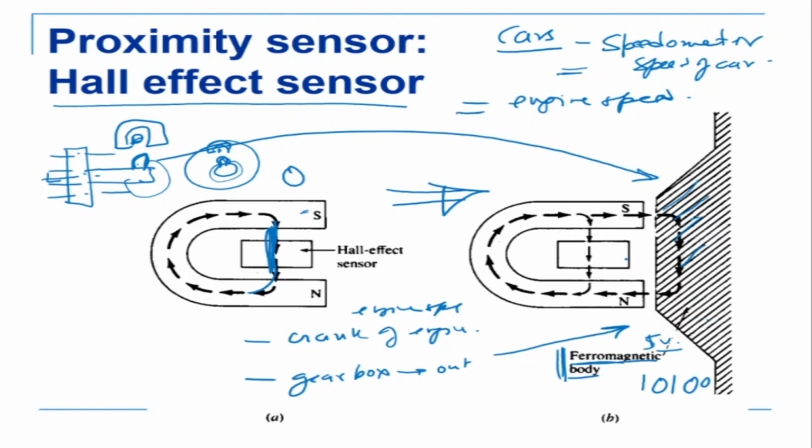Now when we talk about the DC motors, the brushless, what we call BLDC, I'll come to this subsequently. When we talk about brushless DC motors, they do not have brushes. So we need to sense the position of the armature. Armature position is to be sensed.